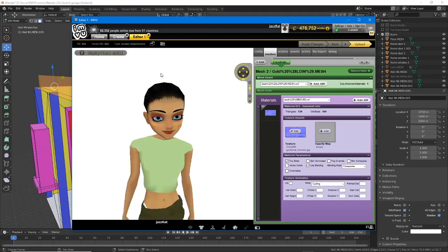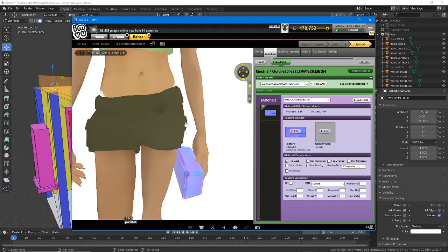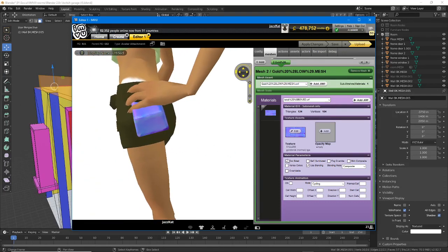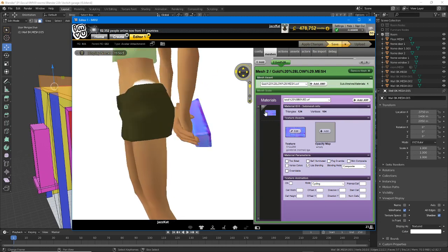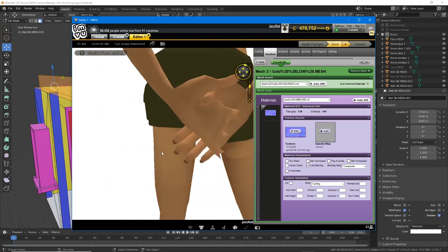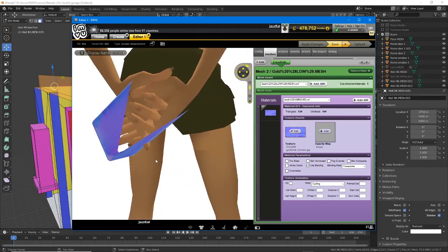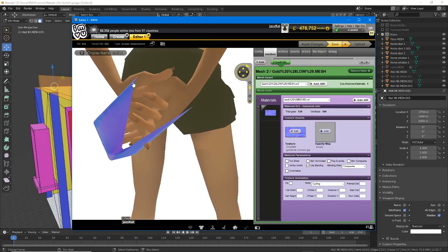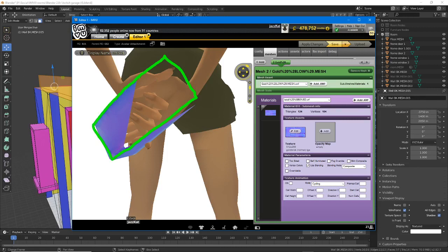so the way to solve that, whoops, why is it not moving? Oh, there we go. The way to solve that is not to enable double-sided, is to make sure that the surface is pointing in the right direction. So if we're moved too close to the object here for the sake of argument, but if this back face was not visible like this, so this section that we're seeing here, let's assume that that was the entire back face and that entire thing was invisible.